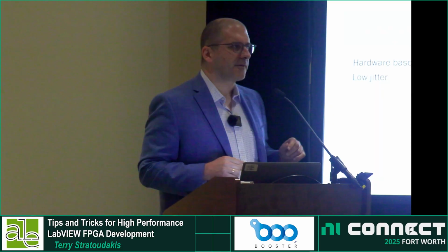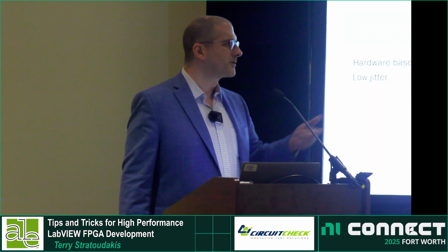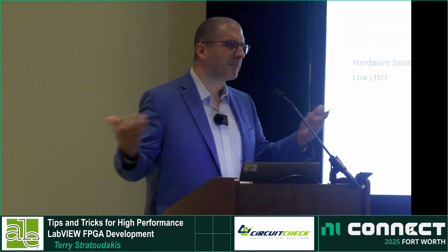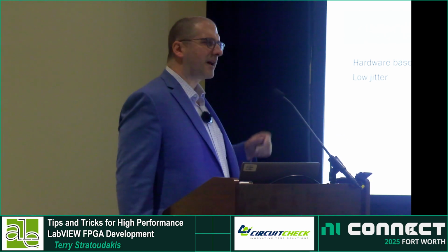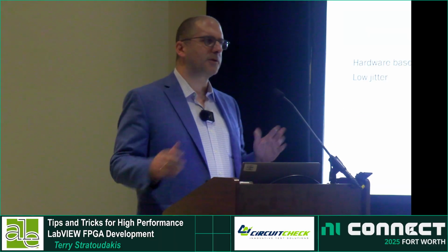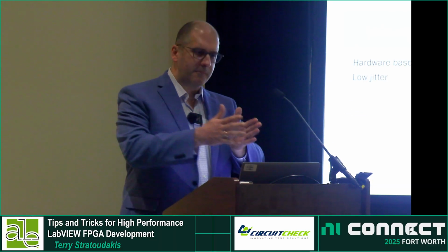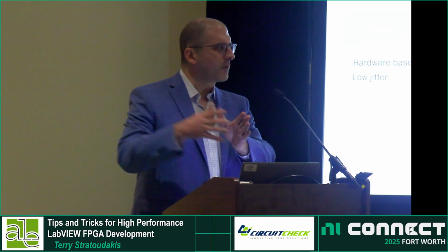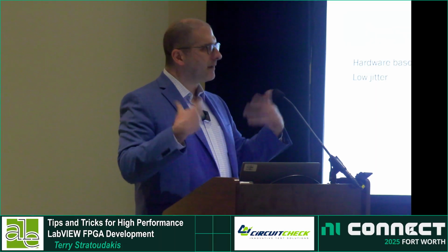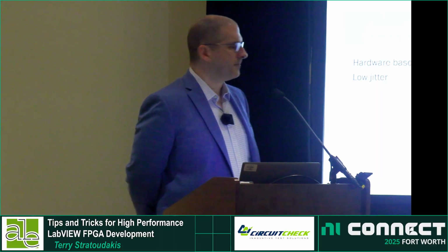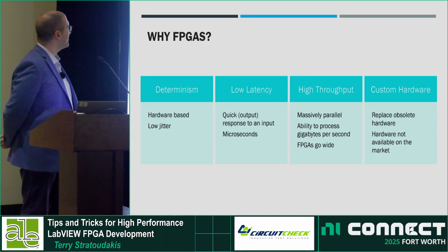And the way they accomplish that, right? So people see that FPGA clock speeds, it's 100 megahertz, 200 megahertz. I'll say, well, my CPU's at gigahertz. What's the deal? And kind of like lanes on a highway, we don't make the speed limit higher, we add more lanes. So with an FPGA, we parallelize. We can have more lanes, more paths. And so that's where at 100 megahertz, we could run gigabytes of data per second. So they go wide, right? So that's the phrase we say in there.